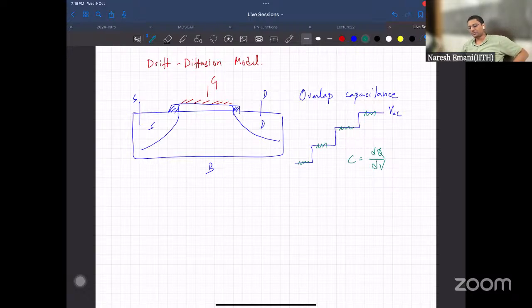For measuring capacitance, you change the voltage with a small AC signal, for example just 50 millivolts AC, riding on a DC signal. You do the small change and then see how the response is. If there's a lag, you figure out how much it is, and based on that, you calculate the capacitance. Now if you have a device like this, depending on the bias conditions, the capacitance can be very complex.